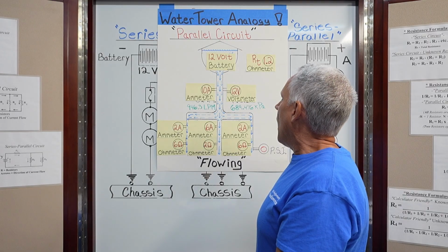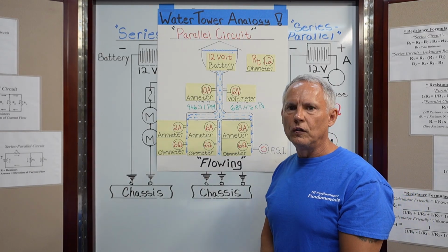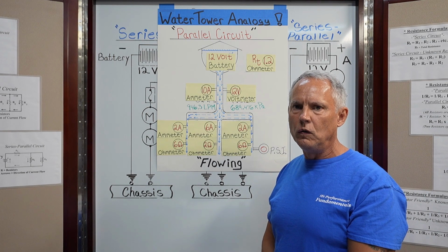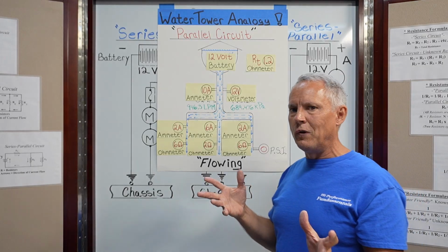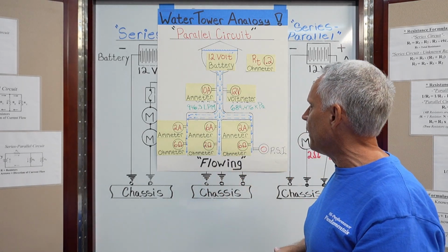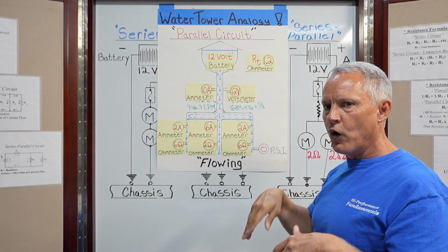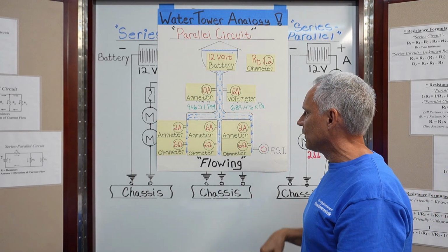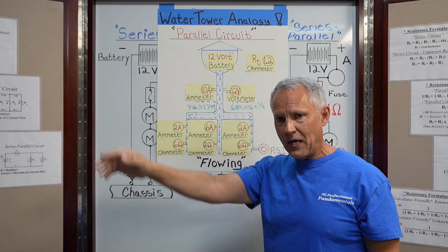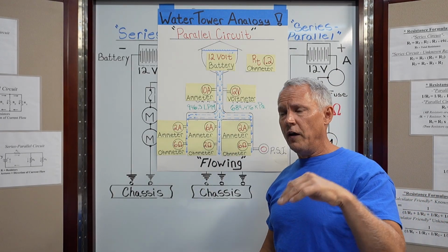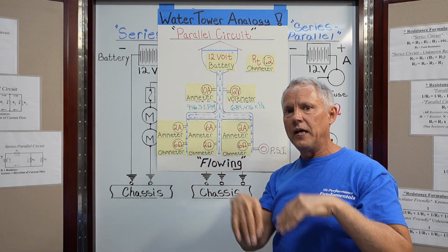Okay, now, without getting really technical and deep diving into that, if you want to look up Kirchhoff's current law, also known as KCL, type in KCL current law, and you'll see what it states and how it's relevant to this situation. We have 10 amps of current flow. That means that the circuit itself must consume 10 amps. If there's 10 amps in, there's 10 amps out. The result is always 0. If you have 10 in, you must have 10 out. Positive 10 minus 10 equals 0.